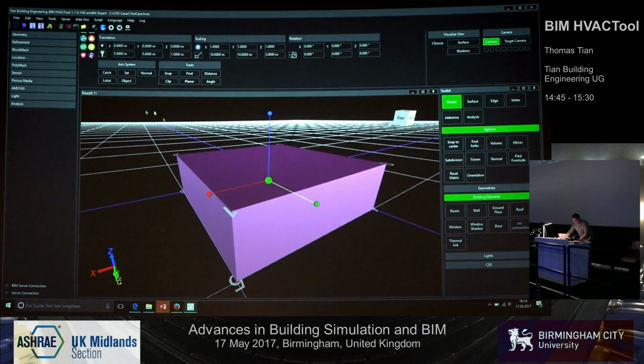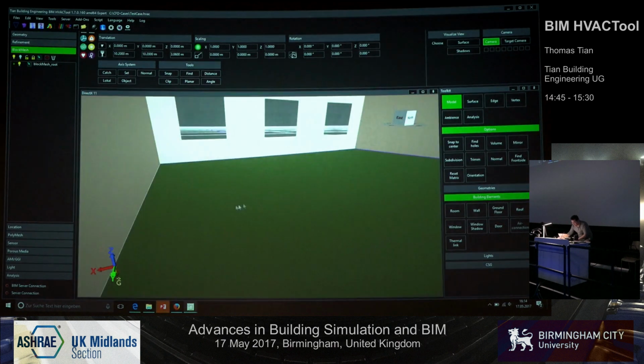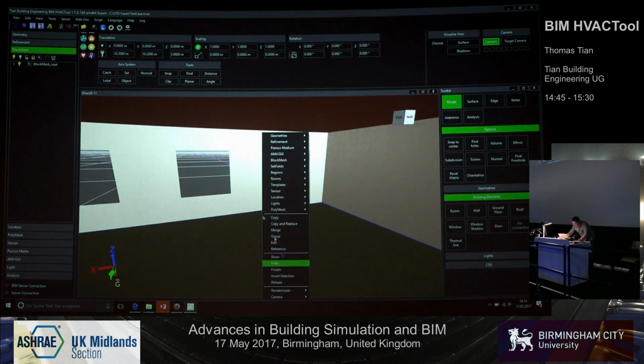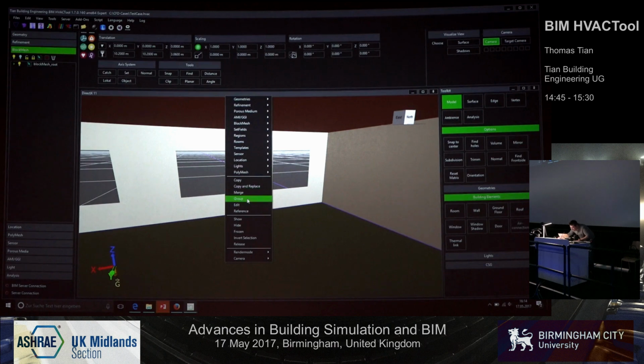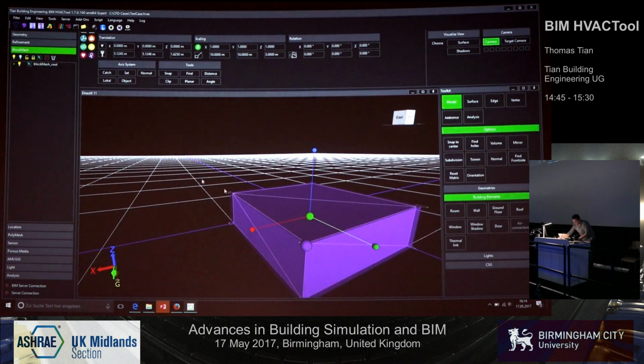Then we make our block mesh a little bit bigger, because the plane cannot be the same size as the block mesh, so we make it a little bit bigger. And then we give it some information that I want to hold my mesh inside. My location point, create a new location point. That's all.